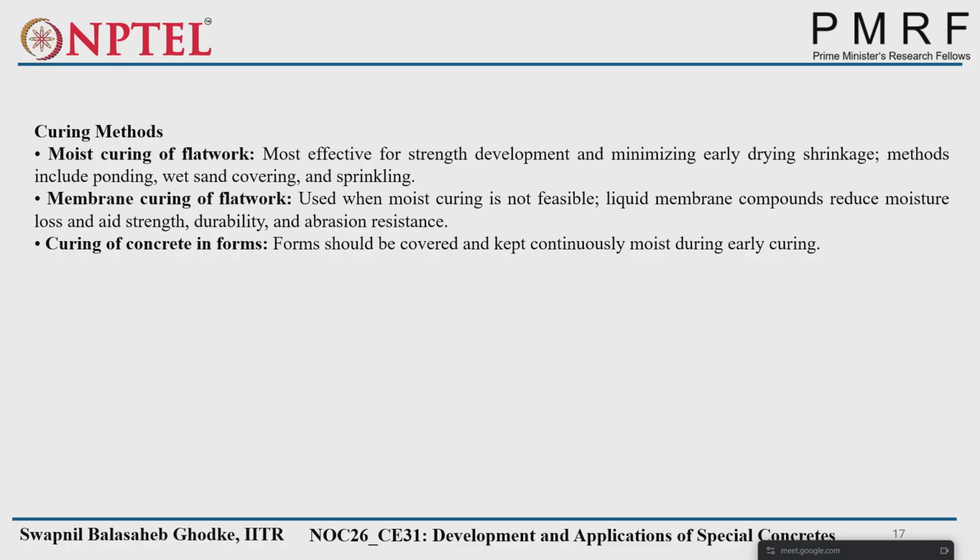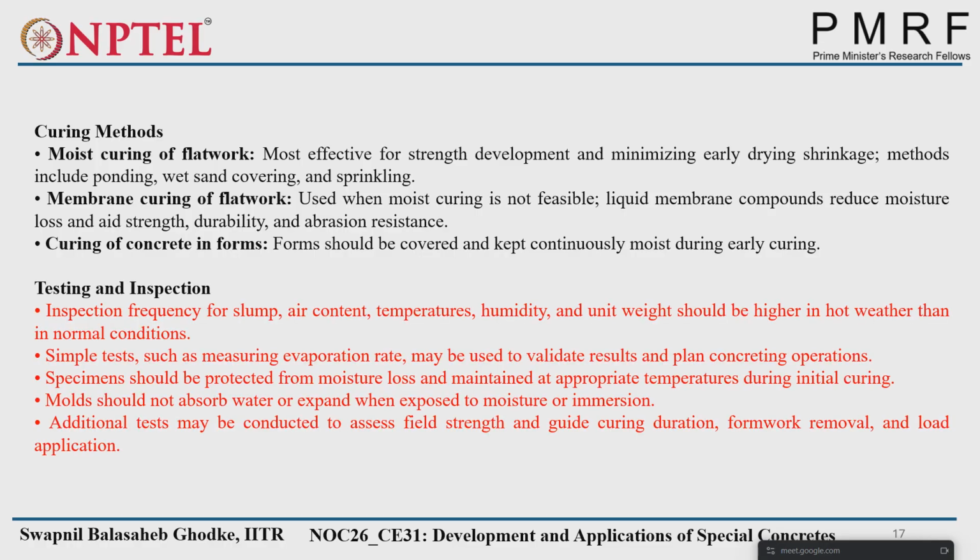Membrane curing is used when water ponding is not possible, when there is water scarcity. At that time we provide the membrane to avoid moisture evaporation from the surface itself. Curing of concrete in forms should be covered and kept continuously moist during early curing.